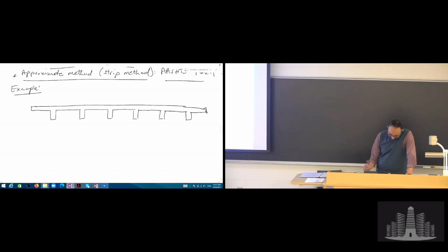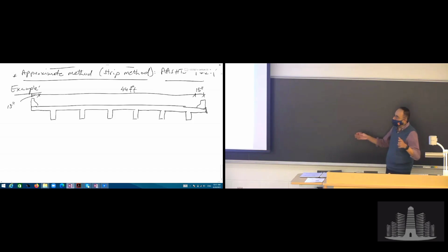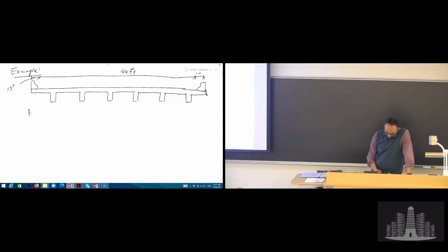I'm just going to assume that this is a bridge I would like to design. And the bridge, these are the barriers. The dimensions are given to you as the barrier width here, the base is 15 inches each. And in between we have a 44 feet width. It's the clear span between the barriers. And we have here the overhang right there is 3.25 feet, for example. And this is 5 spacings or spans between the girders, 8 foot each. So that gives us 40 feet.